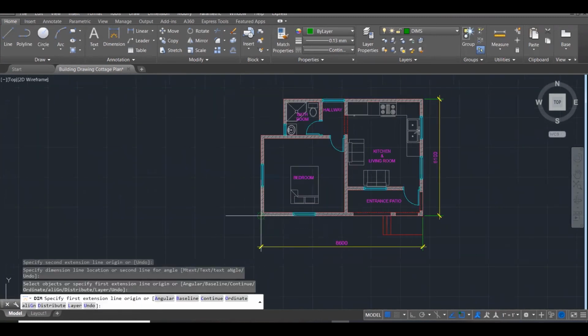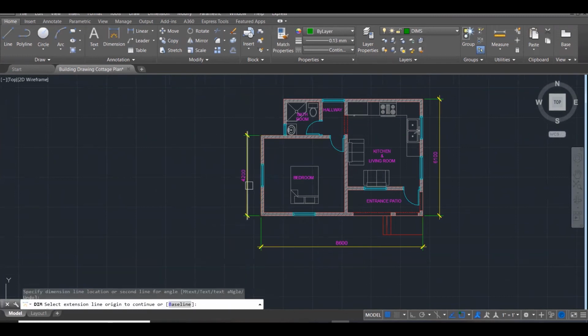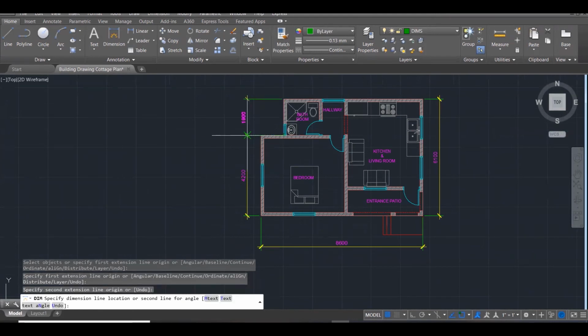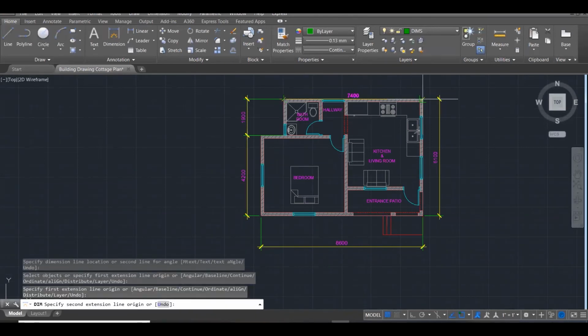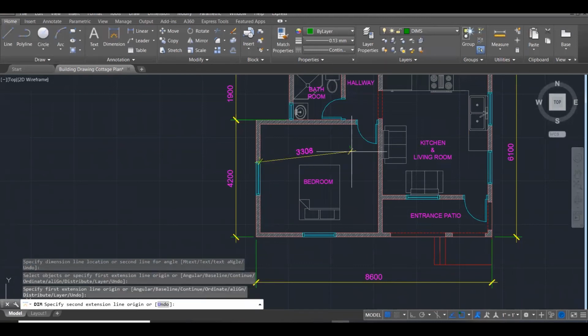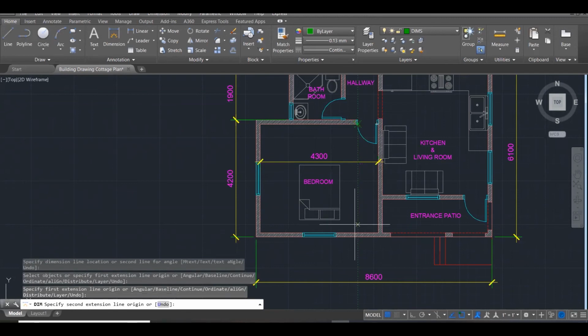That's another dimension that's useful. So that's 3. It's another one that's useful. 1, 2, 3, 4, 5. 5 on the outside, 5 on the inside. So I come here to here. Let's get the size of the bedroom. There. And put on my ortho to help me.